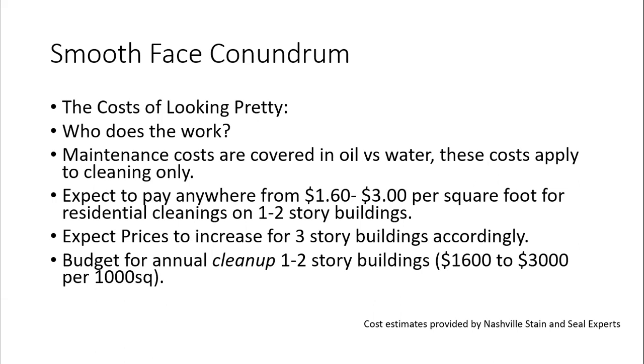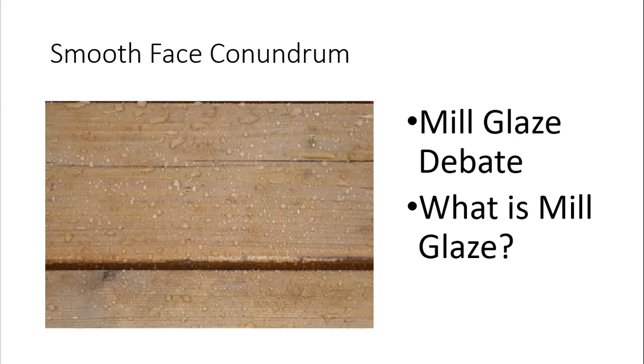So with those cost projections, we're talking about cleanup now. For just washing the car, oxygen bleach, figure $1.60 to $3 a square foot. So per 1,000 square feet every year, figure 1,600 to 3,000 bucks for cleanup. All right, so the smooth face conundrum goes further than